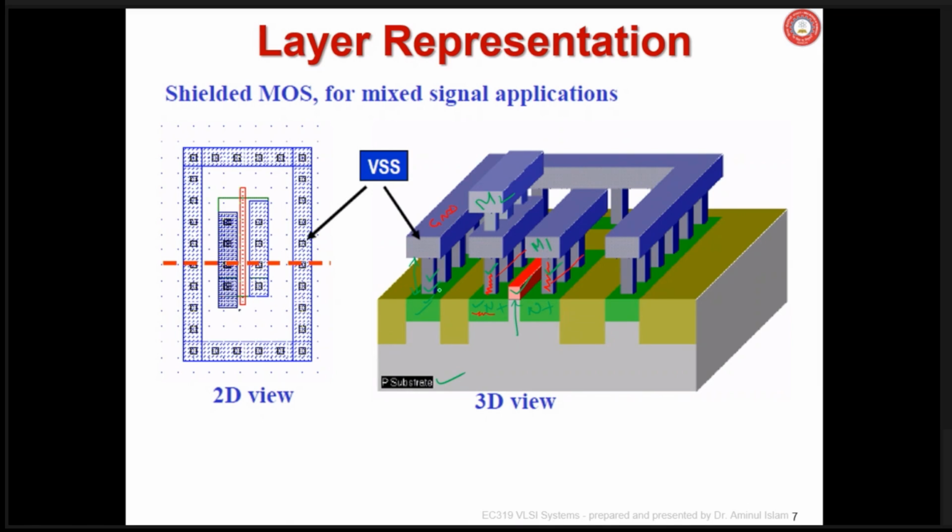Around the device and MOSFET, it is grounded, maybe for prevention of latch up, etc. Anyway, the point here is, if only one hole and via is there, then the possibility is there that the connection will not be there. So to avoid that, multiple connections are shown around it, on top of it.